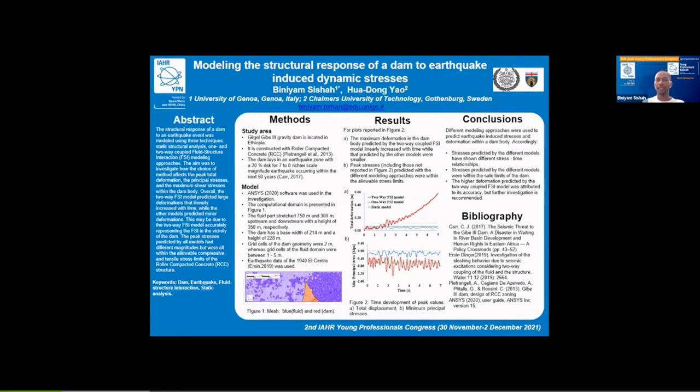In terms of the fluid domain, 1 up to 5 was used, where 1 was close to the dam, and somewhat toward the downstream section where we expected to have a flow on the spillway, because this also is a two-phase simulation. The water level up to the maximum reservoir water level was water, but above that was air. The refinement you see below the dam is to capture the turbulence when the flow dissipates over the spillway, but that was not that important.